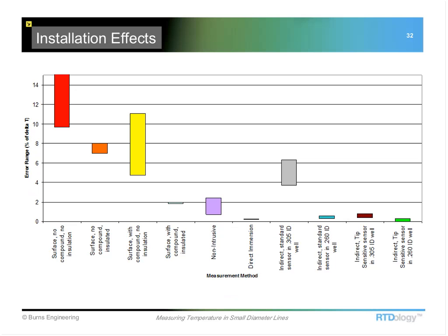Say Bill, along those lines, we've got a question from Rick on the insulation and how much insulation is required to eliminate stem conduction. Well, 3 or 4 inches usually is enough so that you're going to see a significant cut in that error.